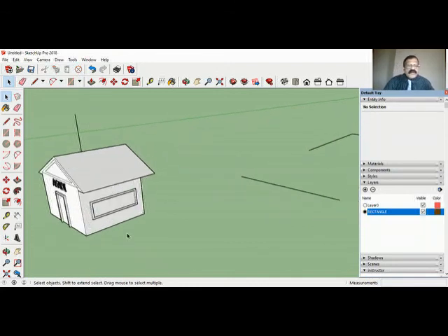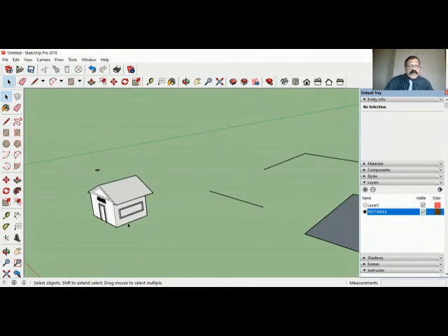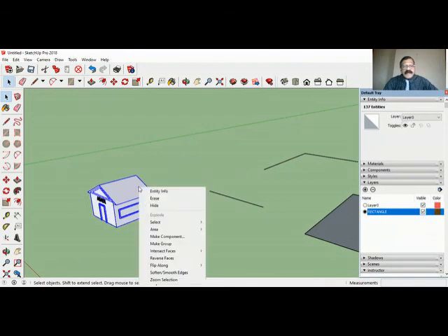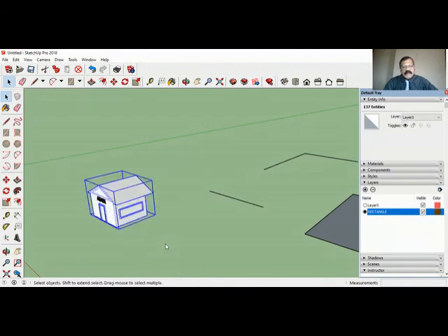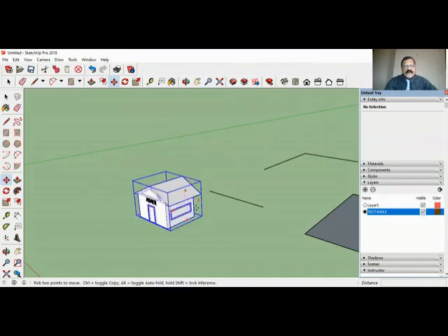Okay. Now you see that these are different pieces. If you want to move here and there, it is very difficult. Sometimes you will forget, suppose I want to delete it or move it. I can press 3 times, but there are more objects and it is confusing. So what you will do is create a group. You click 3 times, select everything, right click and say make group. So it's a group now. Now moving is very easy. You just select only one item and can move. You can make grouping also.